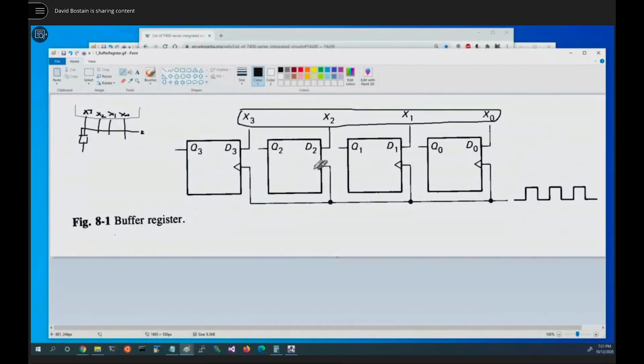Notice I said sometimes they'd be flipped. Well, we put the edge trigger over here and we know it's a D flip-flop with only Q. We're actually looking at, in terms of output, these pins right here. They are the memory of whatever we latched in when the clock went high. We know clock goes high because there's no bubble on the thing.